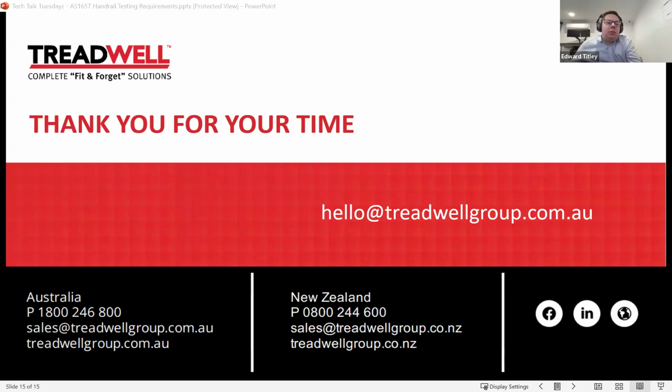And that might tie in a little bit with the question or the comment we had earlier around testing in situ. But you're very correct. If there's any deterioration of the handrail due to corrosion or maybe some sort of impact that's caused some damage, if the handrail exceeds the deflection limits, then it would be deemed to be non-compliant, and on that basis, you'd want to look at replacing it.